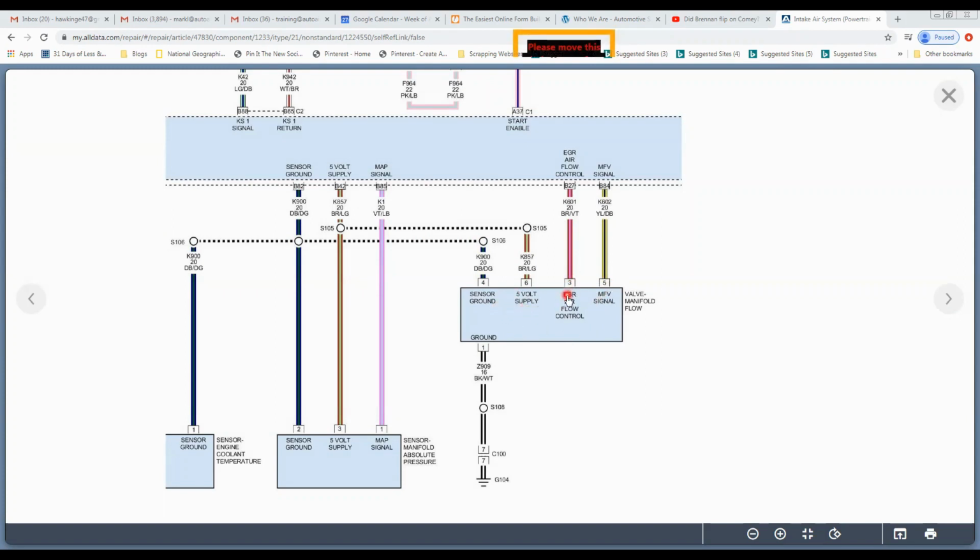And then finally, I've got the solenoid that drives the valve. So what I've got here is the control signal and ground. Because this thing is permanently grounded, that would mean that this thing is power side operated or power side switched, which means the voltage on this wire should be fluctuating between 0 and approximately battery voltage. And the voltage on this wire, because it's a ground, should be pretty close to 0. So that's kind of what we're looking at, or what we hope to see when we actually get our scope hooked up and start testing the circuit.